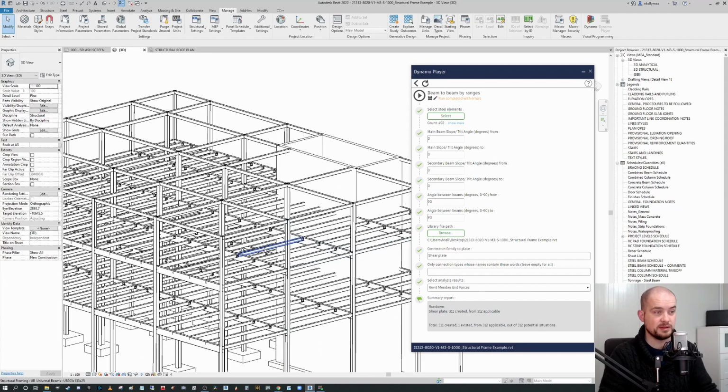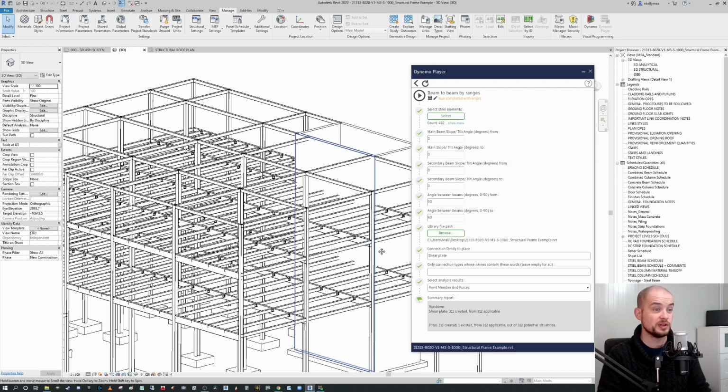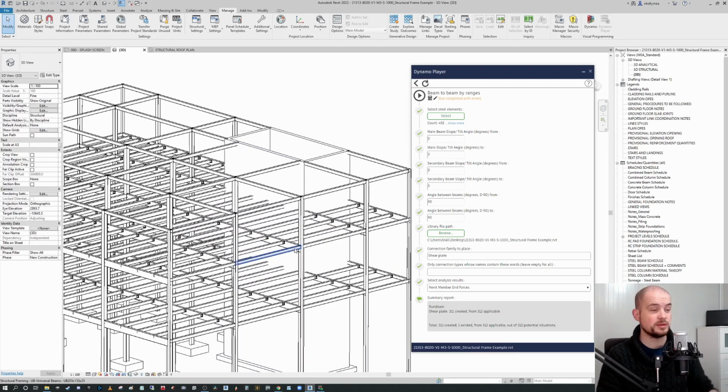And to be honest with you, this is mind-blowingly straightforward. It takes a little bit of tinkering to figure it out. As with the steel connections dialog generally, it can be a little bit clunky. But the fantastic thing now is we just place the one. We don't need to copy it around, we don't need to use arrays, we don't need to move it to the beam and then potentially lock it so that there's no interference or changing should the beam location change. We can merely just use our script now, and everything is there, and our connections look great, and we seem like we're spending much more time and energy on detailing out our models than we actually are.